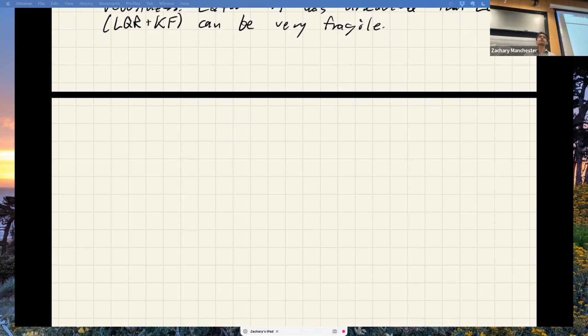So we're not talking about noise. In fact, for linear everything, LQG is optimal and the best you can do. You can jack up the noise really high and the performance will get bad, relatively speaking. You'll get higher cost, but it's the optimal thing. It's the best you can do, and it's not unstable. Whereas we're talking still in the realm of linear systems, right?